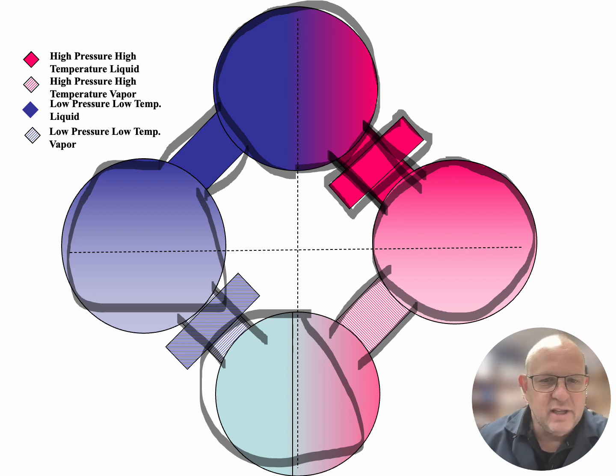The compressor is very self-explanatory, as in its purpose is to compress the refrigerant from a lower pressure into a higher pressure, and to move that refrigerant throughout the entire system, creating on one side of the system a high pressure and creating on the other side of the system a low pressure for us. Hopefully by this time you have drawn the four different circles within the refrigeration diagram. You've connected those circles with the lines that are running between the two, and we will get into the states of the refrigerant. Okay, here's the compressor towards the bottom of it.